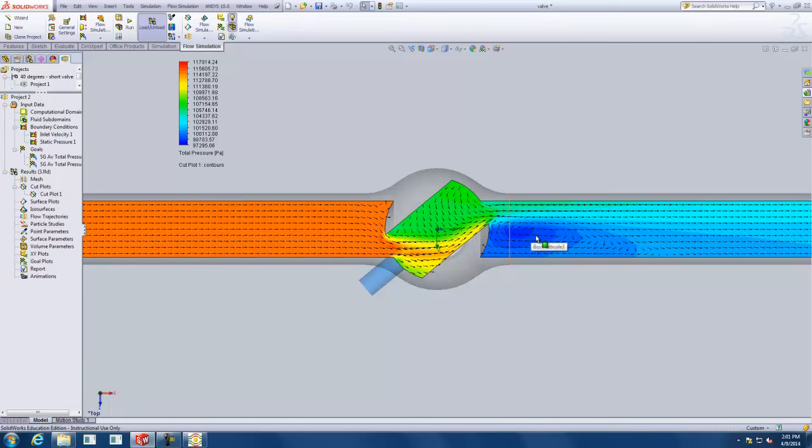All right, so the color contours are the pressure, and the vectors there are still the velocity vectors. So now you have two pieces of information shown at the same time. So we got this high pressure up here. All right, see a big pressure drop here from, say, orange at around 113 kilopascals to green, which is 107 kilopascals. And we have this low pressure region in the middle of the vortex where we expect it to be. All right, so it's a lot of information we can see now.